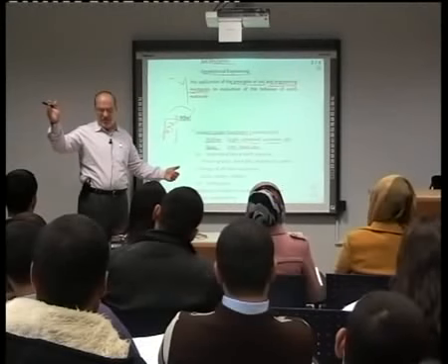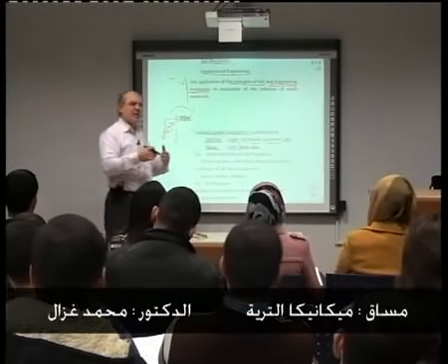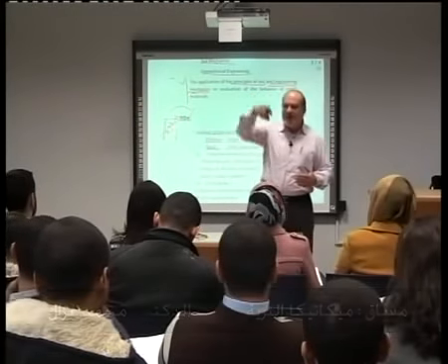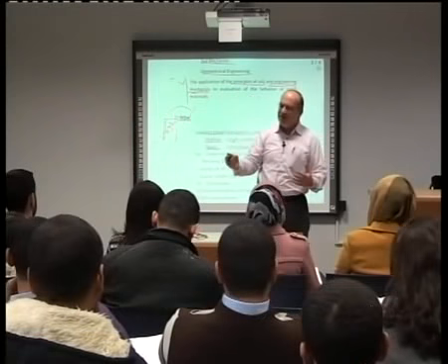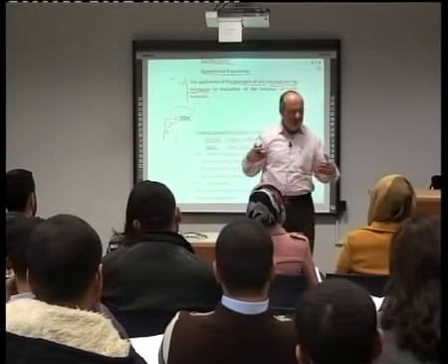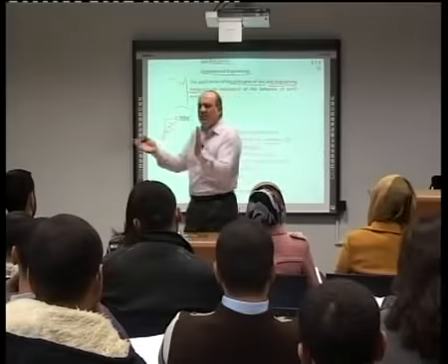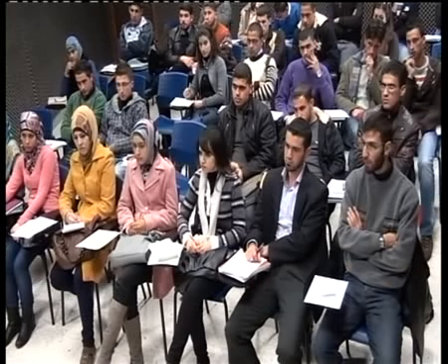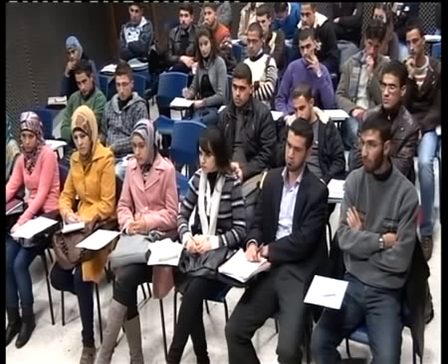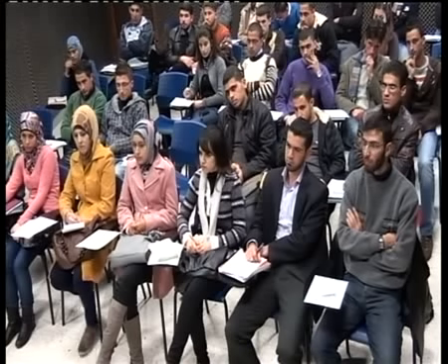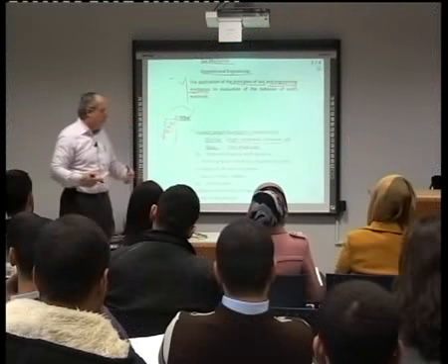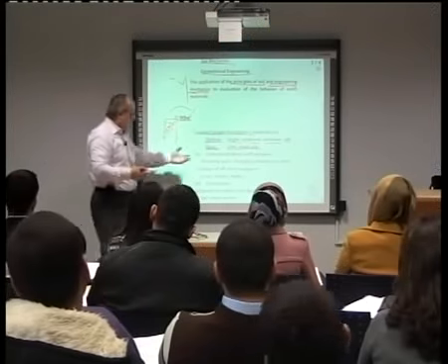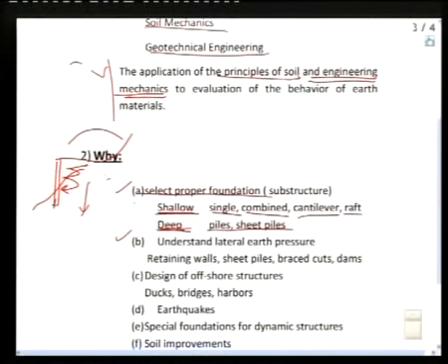Retaining structures are subjected to lateral loads, not vertical loads. Sometimes they are subjected to both. But mainly, retaining structures are subjected to lateral loads. Is it different than vertical load? Of course. Behavior is different, analysis is different, design is different. Okay? So, if I am to design a lateral retaining wall, sheet piles, braced cuts, dams.